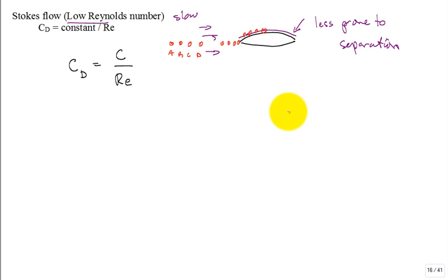Speeding up. So maybe we should write these down. In this section right here, the fluid is slowing down. Why? Because it's seeing the front of that object. If it was a Pitot-static tube, what would theoretically that chunk of fluid that is just perfectly aligned with the very tip of the Pitot-static tube, what speed would it slow down to? Zero. It would slow all the way down to zero.